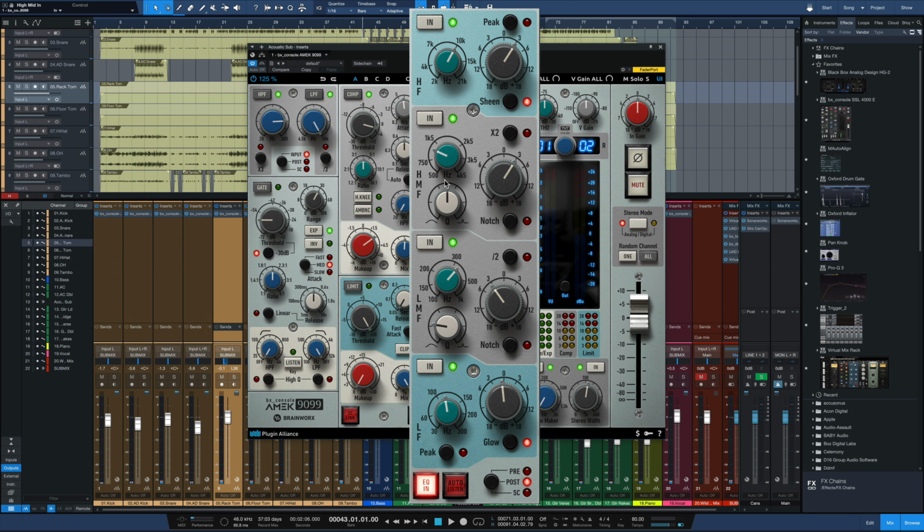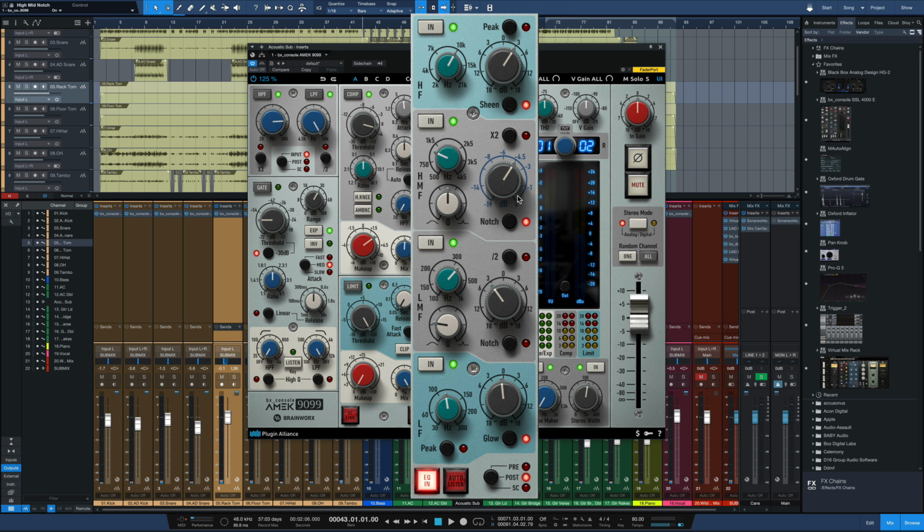For the high mid band here, we've got an on and off button, whether it's in or not. You can change the frequency selection from 500 to 4.5K or 1K to 9K. Makes it pretty versatile, these two middle channels here. And a unique notch filter here, which only cuts. You can see 0 to negative 19 dB.